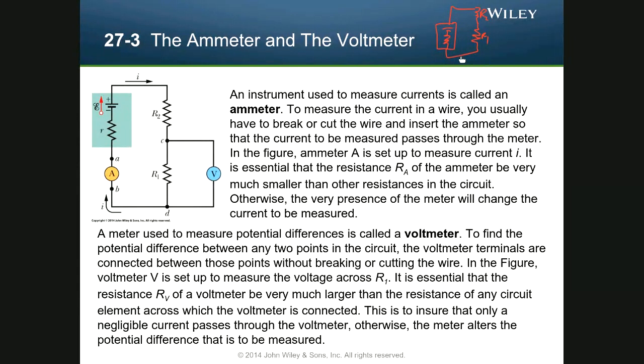Where could you break the circuit up? If it's just one loop, it doesn't matter, you can put it anywhere. But if you have branches, for every branch or every loop you have, you may need multiple places to put in the ammeter. For each circuit element, you'll want a reliable place to put the ammeter. But then you need to probe with your voltmeter, right? And you could probe either this resistor, or the battery, right?